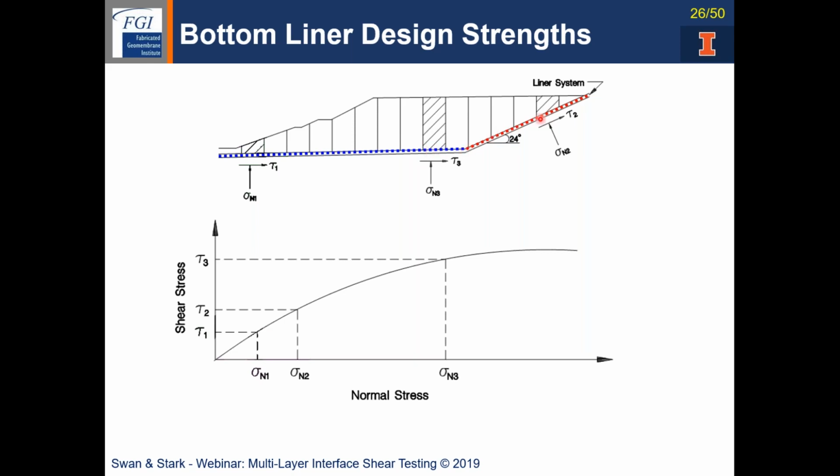But on the side slope, where the red dashed line is that I'm pointing to, that has enough shear forces or shear stresses applied to it during construction that you need a residual strength for your factor of safety calculations. And then apply residual on both of those surfaces and make sure you have a factor of safety greater than 1. The envelope is stress dependent, so you should be using a stress dependent envelope in the factor of safety calculations.